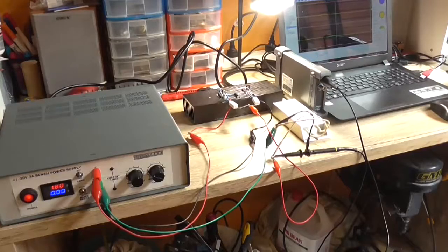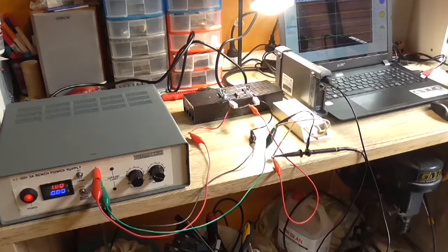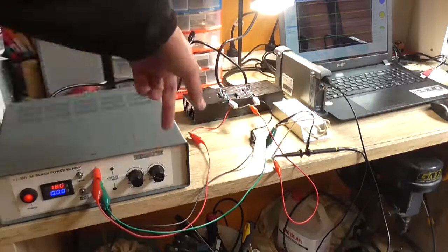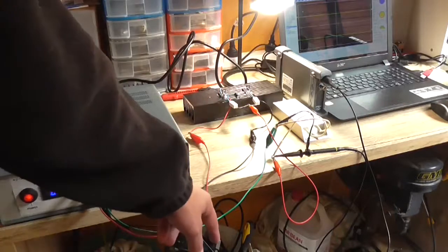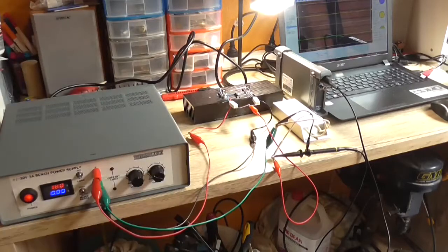Alright, I got everything set up. I haven't got a DDS connected or anything yet. I've just got basically the output stage connected to the power supply. Power supply set to plus minus 18 volt to start with. Current limited down to about 500 mA, just in case it decides to start drawing loads of current. Got a times 10 probe across an 8 ohm dummy load across the output, with the ground being common to the centre of the power supply. Got the oscilloscope in the background there ready to measure at 1 volt per division. Not that we're going to see much at the moment.